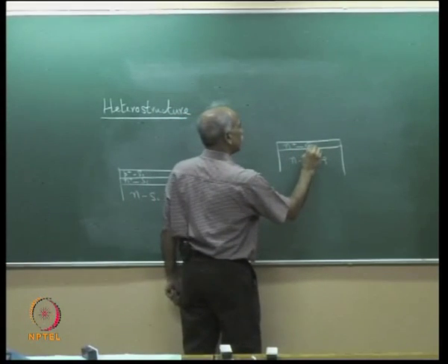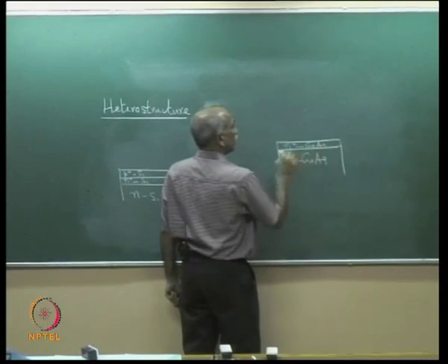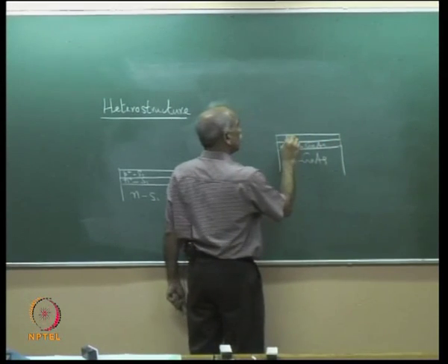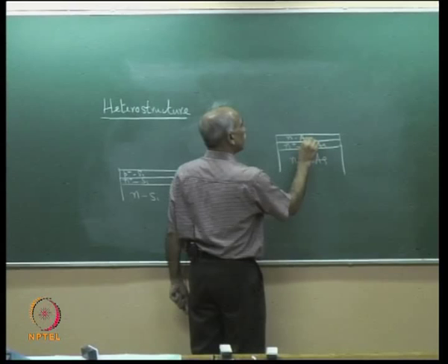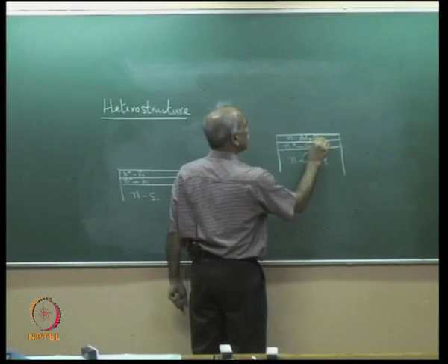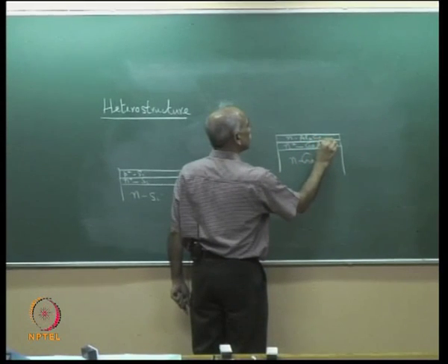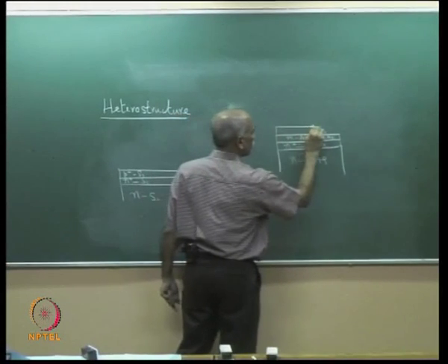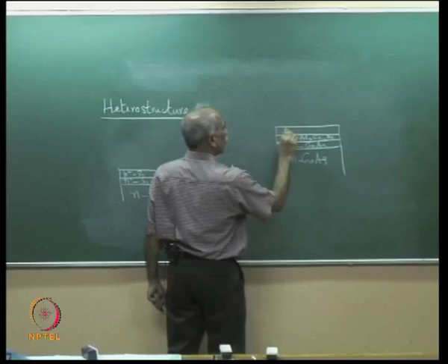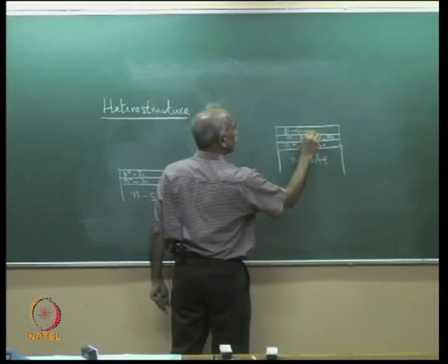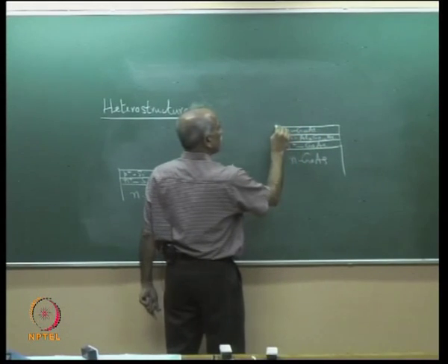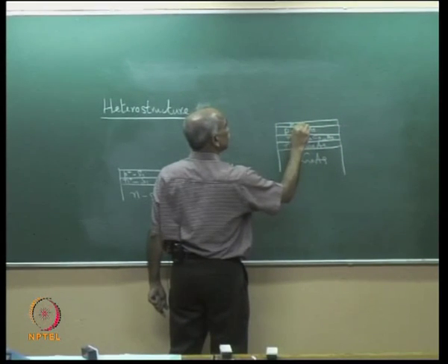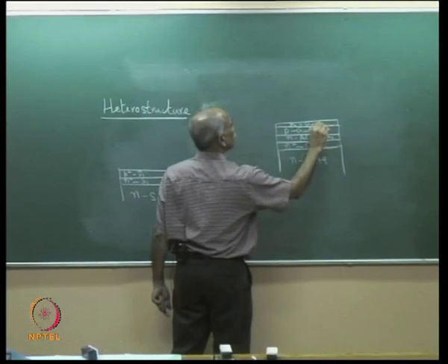So, n plus gallium arsenide, and on top of this if I deposit n aluminum gallium arsenide, AlxGa1-xAs, and then I deposit again p or p plus gallium arsenide and then deposit another layer of p plus gallium arsenide.